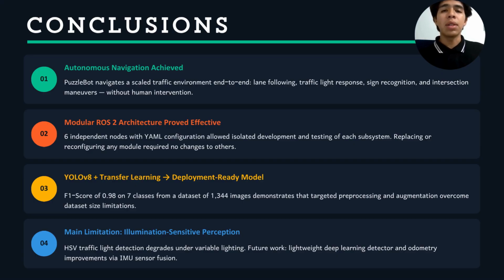The clearest limitation was HSV-based traffic light detection, which struggles under changing lighting. In terms of learning, we understood in practice that integrating subsystems is harder than building them separately. Debugging in real hardware, network latency, variable lighting, encoder issues, that was our day-to-day.